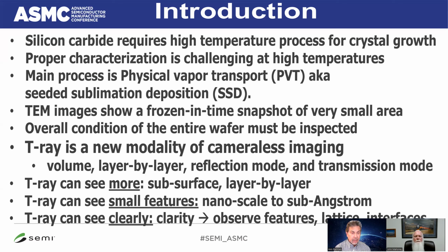It's way more advanced than gallium nitride because a minimum half-meter boule is routinely grown. The only difficulty is that it requires very high temperature, close to 2200 degrees or above, sometimes even 3000 degrees, treatment for the vapor deposition, physical vapor transport, as they call it.